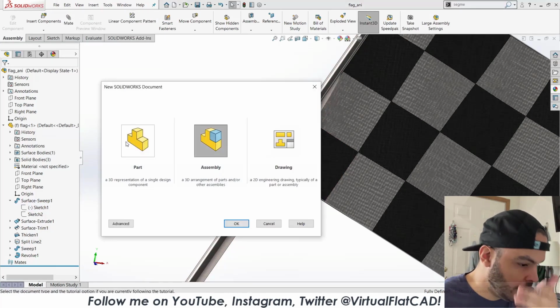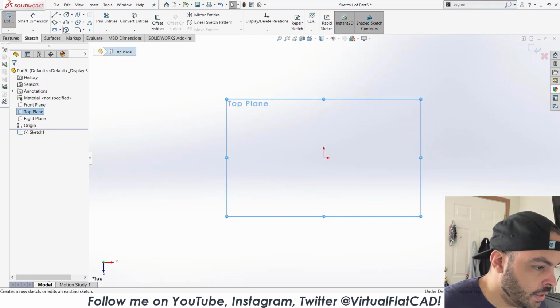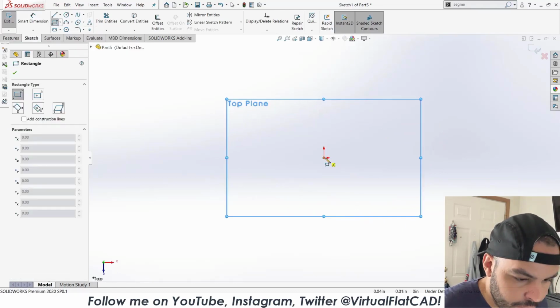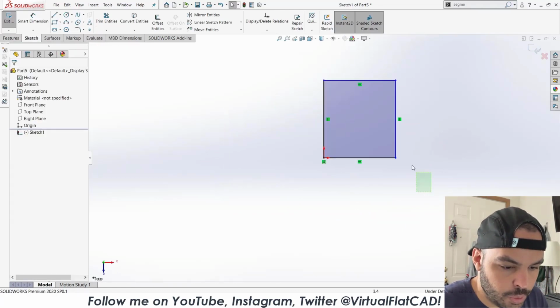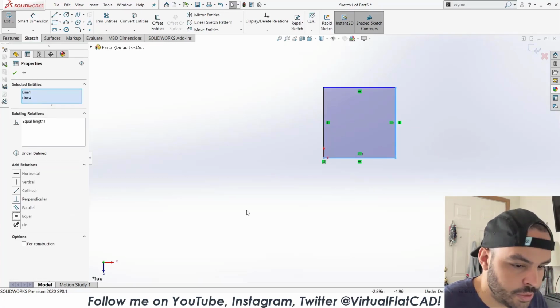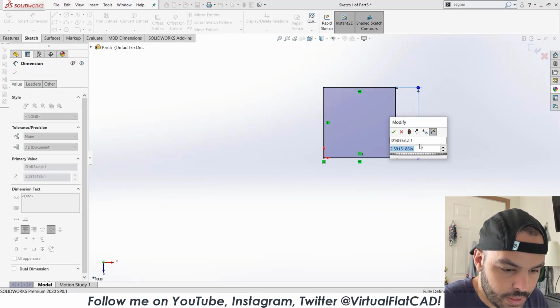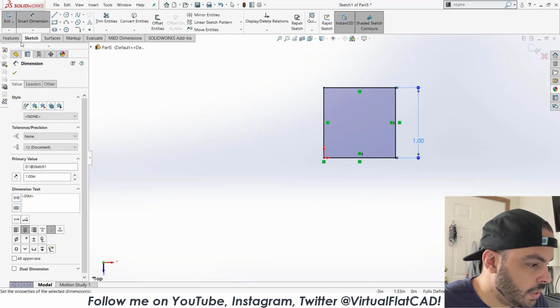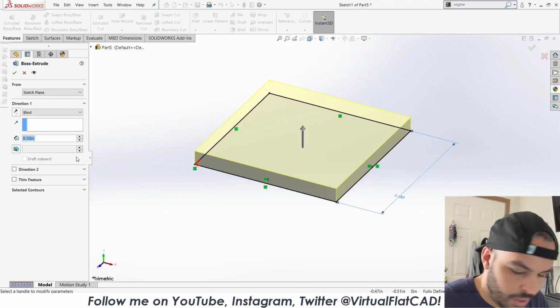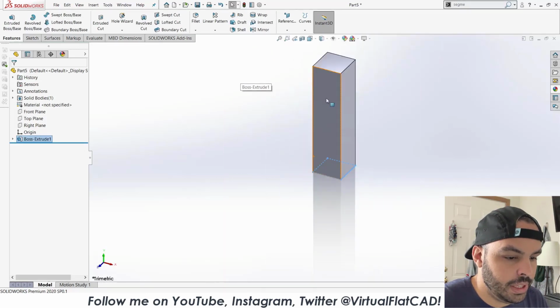So we're gonna start a new part, go on the top plane, and for dummy parts, I just like to make a little square, like a tiny rod, I guess. So let's make those equal. Say it's like 1 inch or whatever, 4 inches tall.